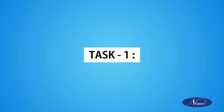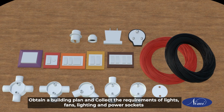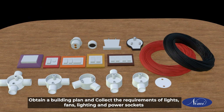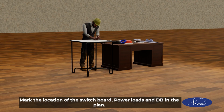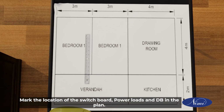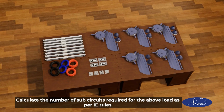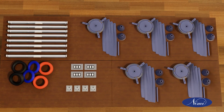Task 1. Obtain a building plan and collect the requirements of lights, fans, lighting and power sockets. Mark the location of the switchboard, power loads and DB in the plan. Calculate the number of sub-circuits required for the above load as per IE rules.